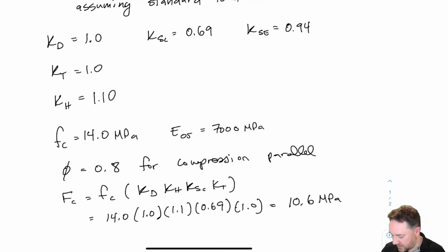Okay, so in this case, we have our buckling length, and we only have a single column, and that column is connected only at the tops. So for both directions, we have the same length, and we have the same effective length as well, because we have pin condition. So the effective length of this column happens to be the same as the actual total length, because we don't have any supports halfway up that are preventing buckling. So it's buckling from end to end, and it is a simple buckling shape, basically, that looks something like this, which means our K equals 1. So effective length, in this case, equals our length.